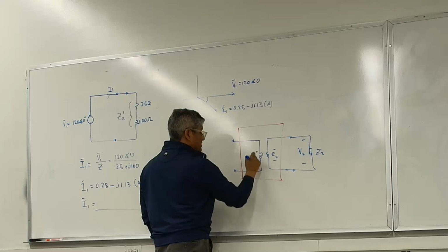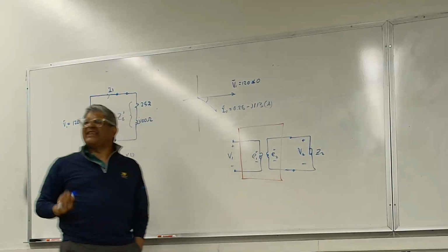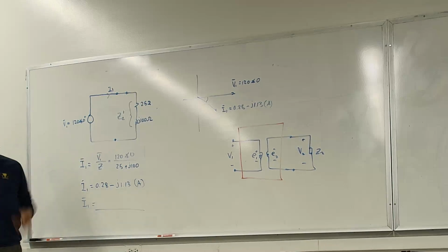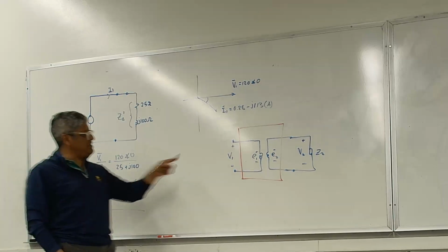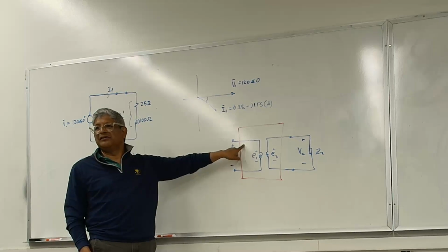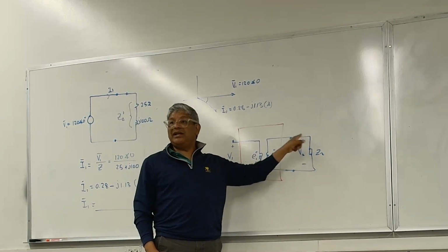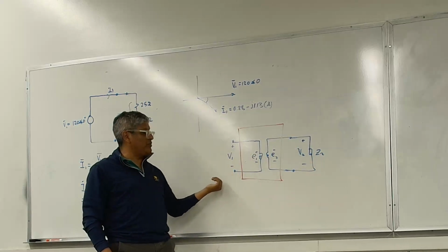There is an E1 plus minus, and there is voltage V1 plus minus. So really the question is this. Somebody's giving you that information, right? And they give you the impedance, they give you the load. And what they're asking you is, can you tell me what is the current on the primary side of the transformer? You can solve it here if you want, and then transfer that current to this side, and we'll do an example like that.